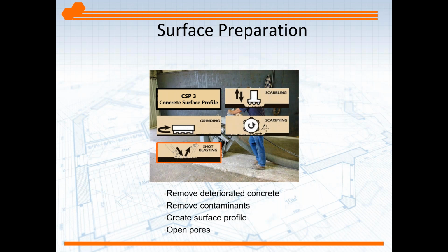But bottom line, for any product you're trying to adhere to concrete, not just moisture vapor products, manufacturers generally ask for or suggest a CSP3 prep. But as I've been preaching all along, read the flooring manufacturer's recommendations, read the setting material manufacturer's recommendations for prep of concrete surfaces.